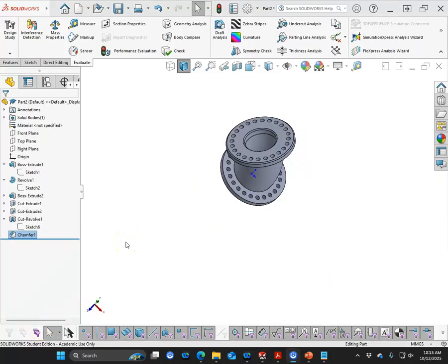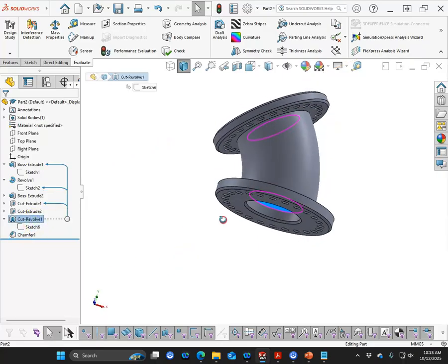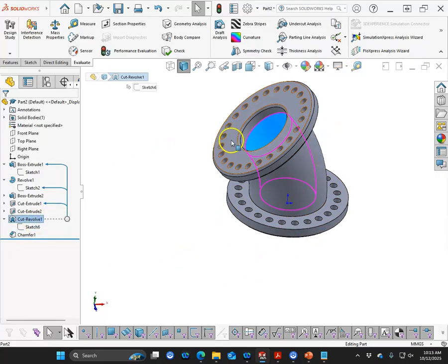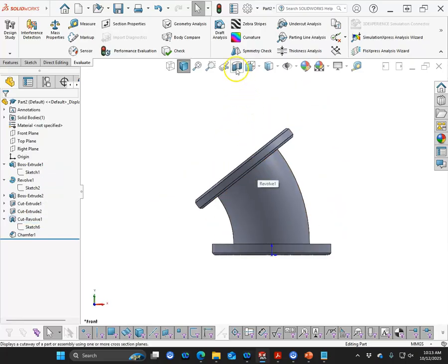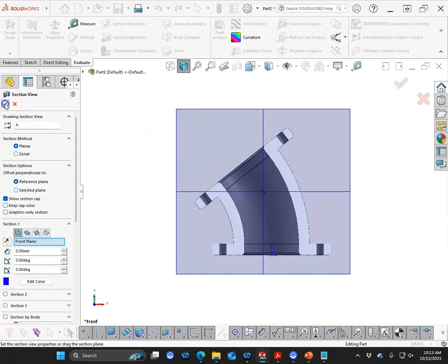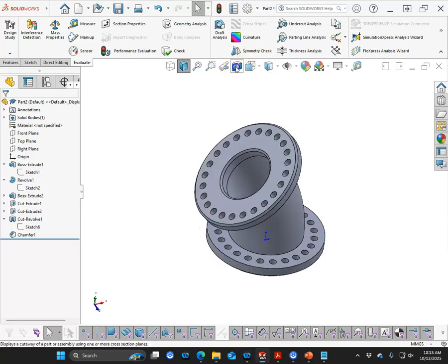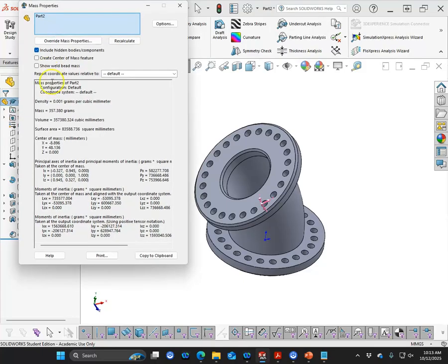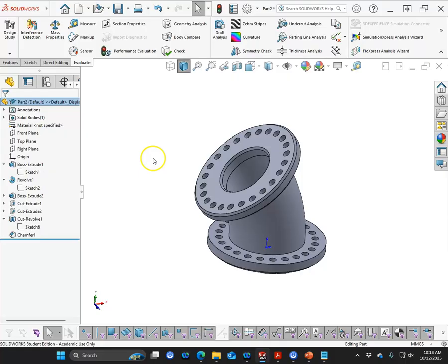Okay, so of course after I stopped the video, I went back and I checked my cut revolve. It actually had 360 degrees, so it was removing some portion of that geometry and nibbling it out. So we do have a cleaner cut, making sure that it actually takes the 38 degrees. And let's check one more time the 370. Okay, so it went up to 357, so I still have some issues somewhere. But that little fingernail cut that was bothering me has been corrected.